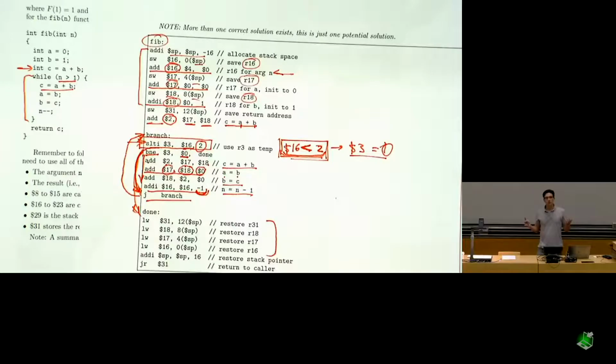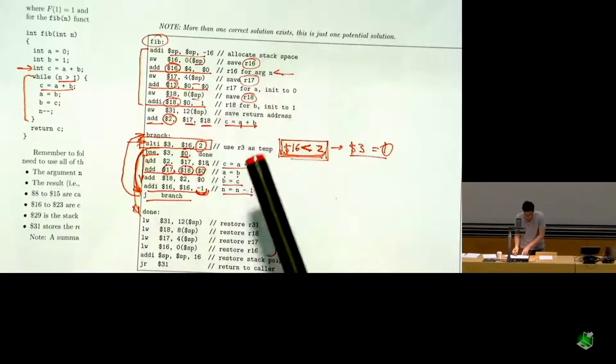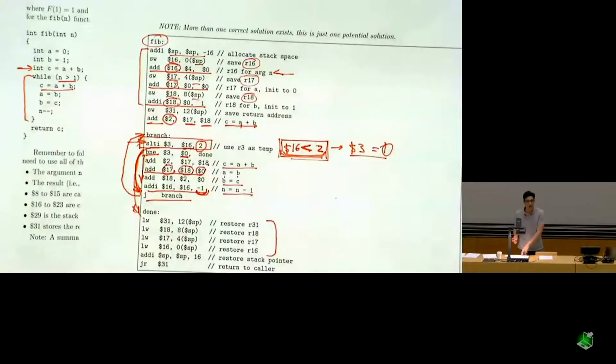In some particular situation, you might be able to do that, but the thing is that you are going to write this function just once. You just want to write this function once. And you know that in this function, there are 3 registers that are used, 16, 17, and 18, and you're going to operate using them. It might happen that sometimes you're really using these registers, other times not. But it is safe to have this convention that those registers that are going to be used by the function are by default saved in the stack. And this way you avoid any possible overwriting.